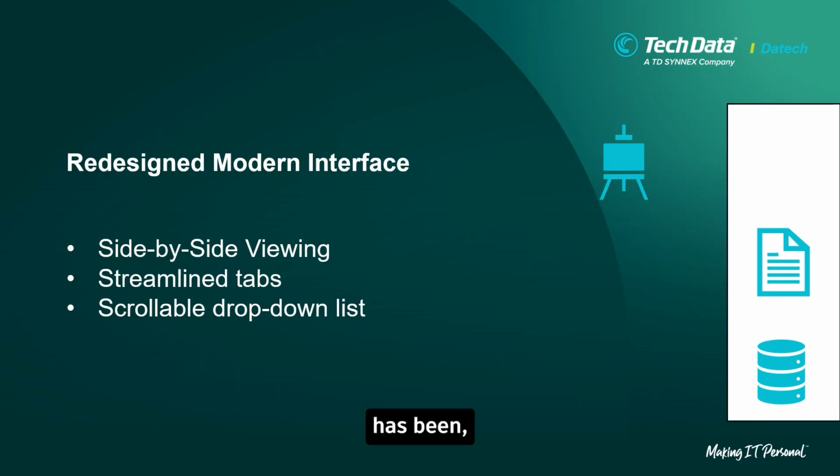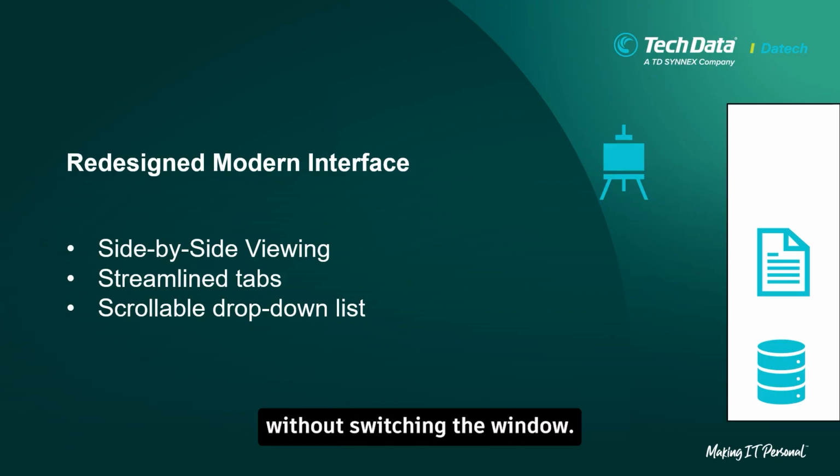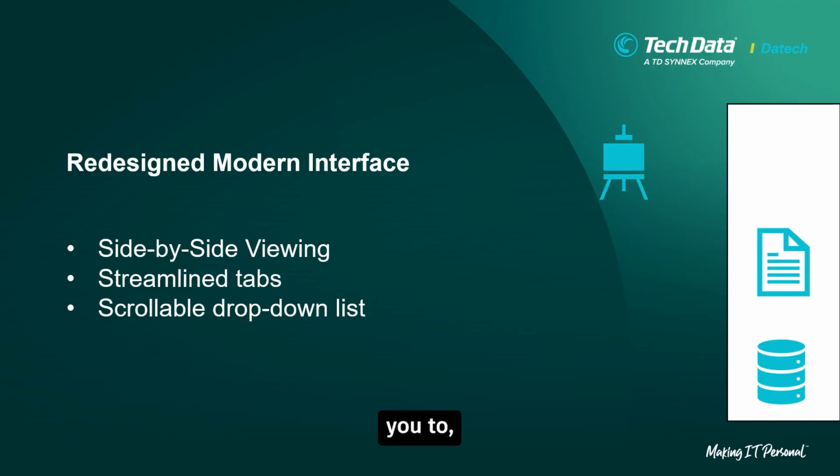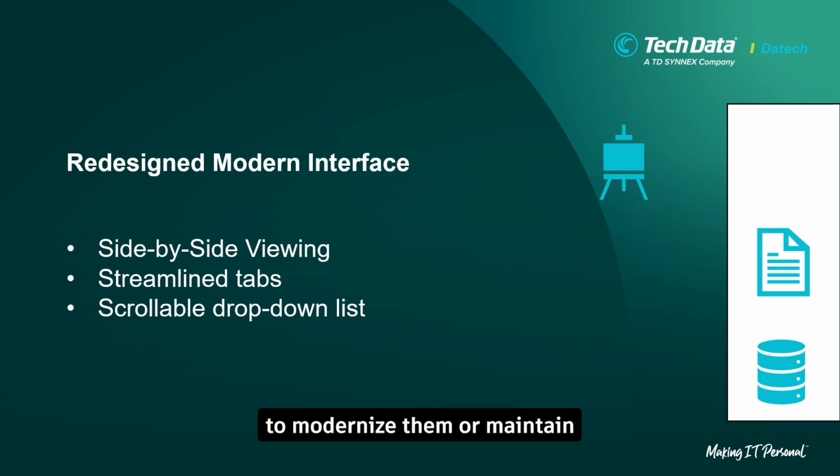When a spec editor is being utilized by a designer, it is a redesigned modern user interface, we can say. This redesigned interface helps you work on the piping specification catalog, allowing immediate comparison and editing without switching windows. It also helps you work on three core tabs: spec, branch table, and catalog, modernizing them while maintaining the essential functionality.